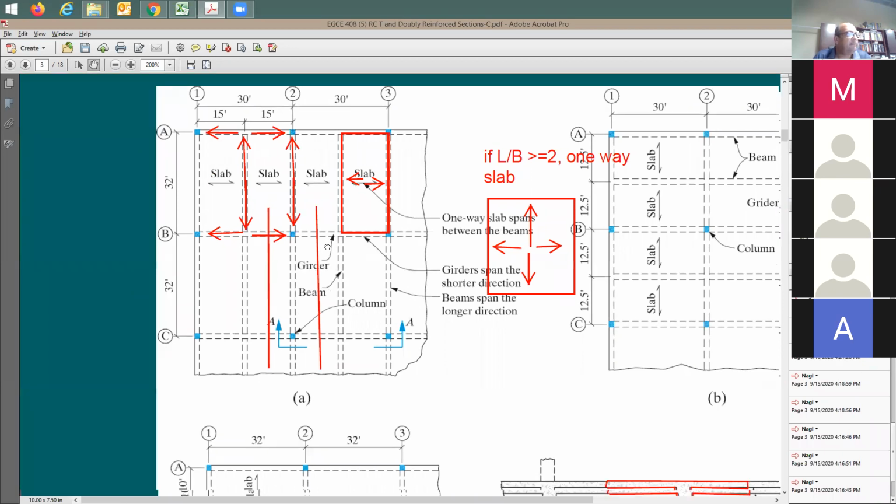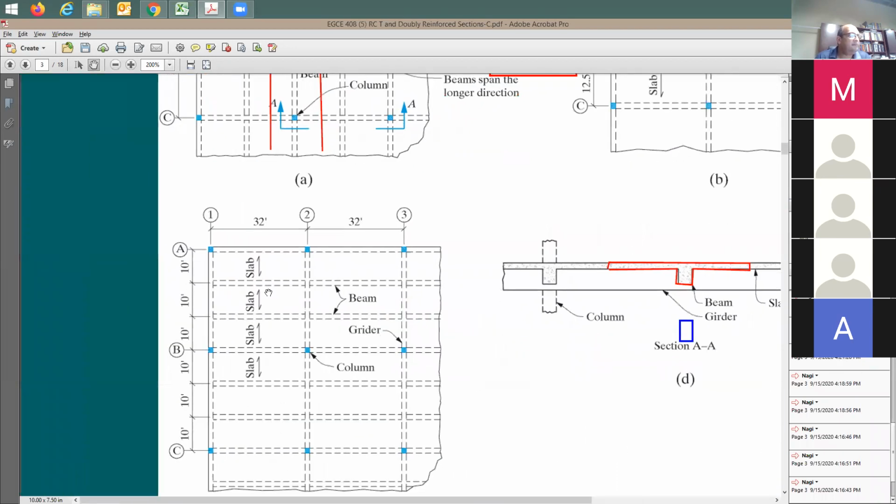So I'm going to say, okay. How about in this case here? For this beam, where is the slab width? You say slab width here is going to be equal to 10 feet, from here to here. And the distance is going to be 10 feet and 10 feet, so that from here to here is going to be 10 feet. So I'm going to call this the boundaries between beams, the tributary width between one beam and the other, right? But this is not it.